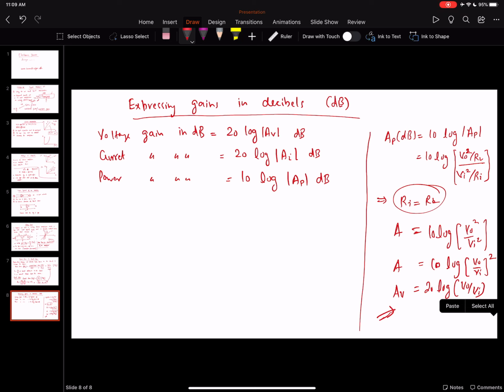Okay, there's one important but quick concept before we end our lecture today. The last thing is, as I hinted previously, that whenever a gain has a negative sign, if our voltage gain has a negative sign, this means amplification, and the negative sign means a 180-degree phase shift of the output relative to the input. So our input will be phase shifted. Okay, so what does this mean?